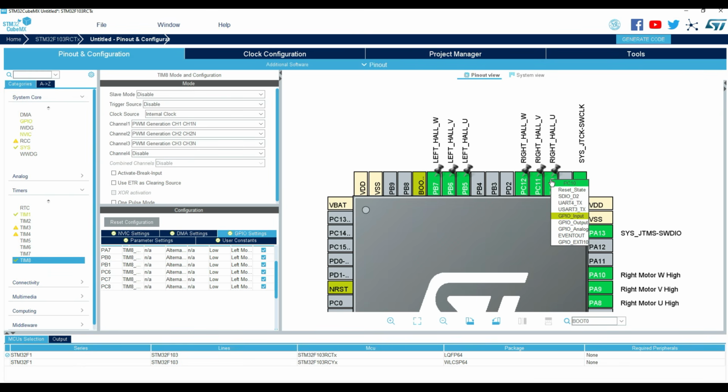They have input capture, read position, and plus speed in hardware. So no CPU lag. And that's why we use PB5, 6, 7 and PC10, 11, 12. These pins are alternative functions of timer 4 and timer 3 for the hardware connection, which we use inside. If we disconnect, what will happen? The motor cannot find the position and won't start, vibrates, stalls in position.